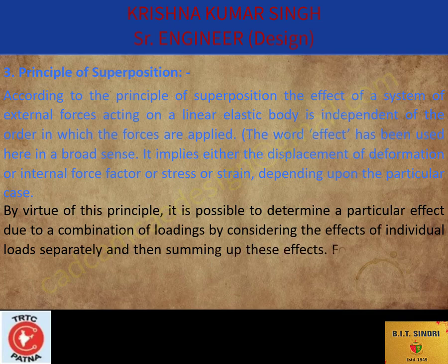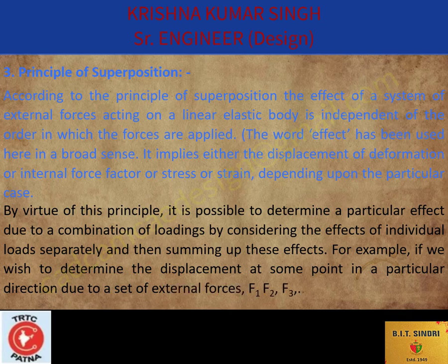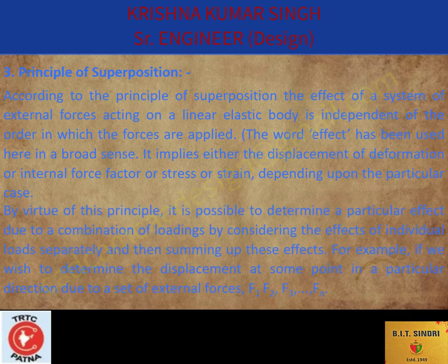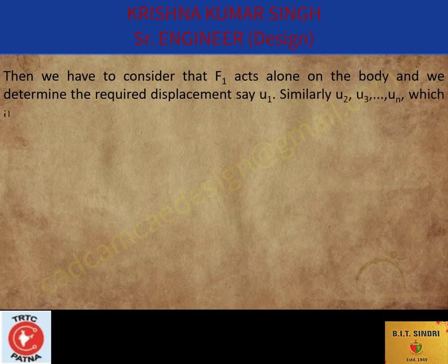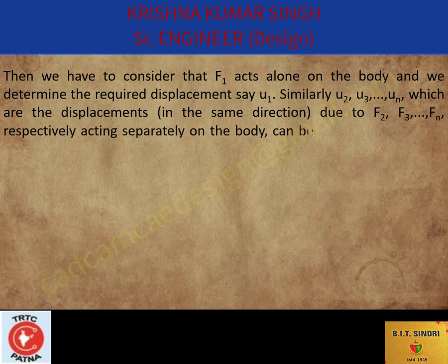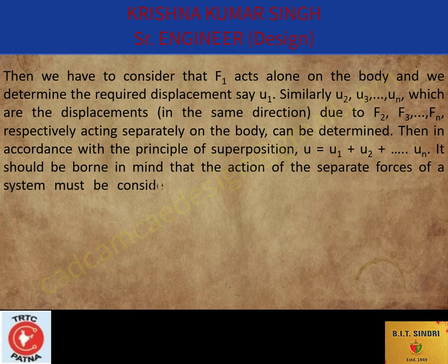effects of individual loads separately and then summing up these effects. For example, if we wish to determine the displacement at some point in a particular direction due to a set of external forces F1, F2, F3, Fn, then we have to consider that F1 acts alone on the body and we determine the required displacement, say U1. Similarly, U2, U3, Un, which are the displacements in the same direction due to F2, F3, Fn respectively acting separately on the body, can be determined. Then in accordance with the principle of superposition, U equal to U1 plus U2 plus Un.